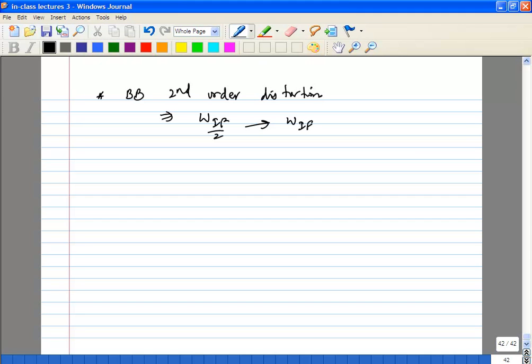Okay, so what can you do to prevent these things? Obviously, reduce second order distortion in all systems, right? What else? Make sure your LO has very good 50% duty cycle, as close to 50% as possible, because if you have exactly 50%, you don't have a second harmonic. Okay?